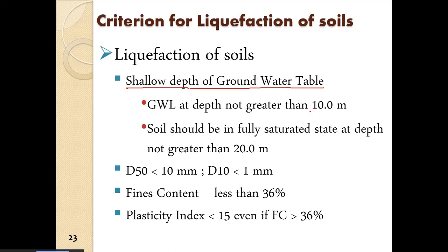As a thumb rule, if the groundwater table is below 10 meter, it is not likely that there will be liquefaction. And up to 20 meter, if the soil is in a partially saturated state, then obviously there is no chance of liquefaction. So this is a thumb rule.